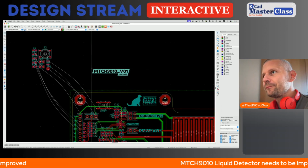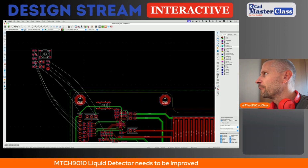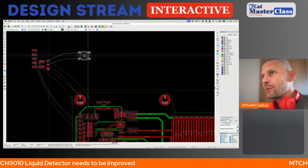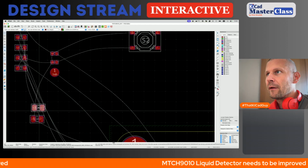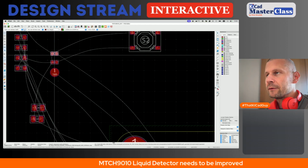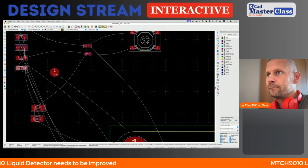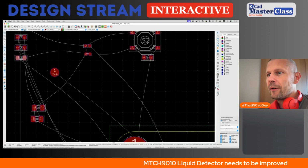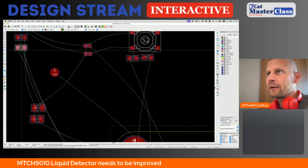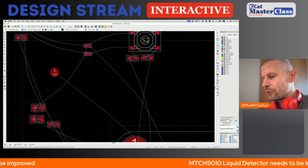Wake up. This is the button. These are 2 LEDs. This is the ESD diode. This is the isolating 0 ohm resistor for the wake up. Here is the 10K for the wake up. Here is the heartbeat resistor for the LED, and here is the output resistor for the LED.